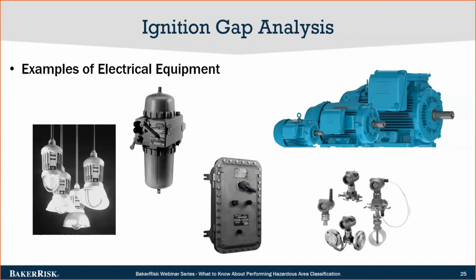Quite honestly, it's quite amazing that in many cases those bolts are not properly torqued or may not even be tight, in which case that renders this box enclosure totally unprotected. So it's important that we record those things and make sure that the equipment is properly maintained.